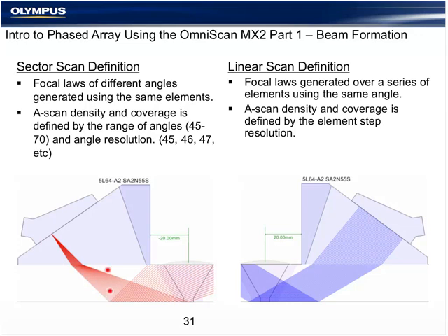This allows a cheaper instrument with fewer elements to be used in phased array inspection. It also generates the pie-shaped display that most people normally associate with it. There are advantages and disadvantages regarding calibration, and the ability to conform with conventional existing procedures and codes. Then there's the linear scan.